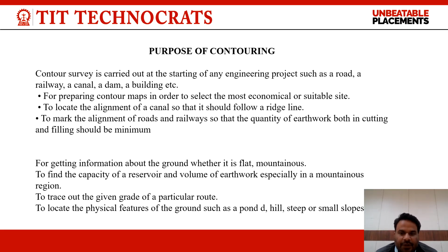What is the purpose of contour? Contour survey is carried out at the starting of any engineering project such as road, railway, canal, dam, building, etc. for preparing contour maps in order to select the most economical or suitable site, to locate the alignment of a canal so that it should follow a ridge line, to mark the alignment of road and railway so that the quantity of earthwork both in cutting and filling